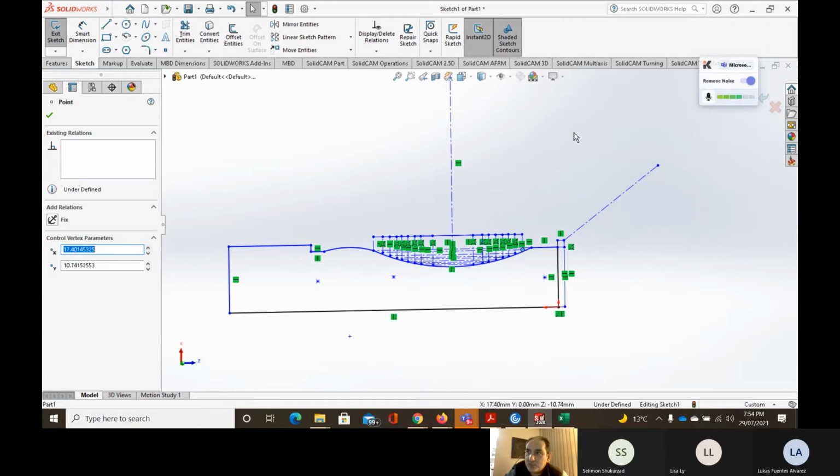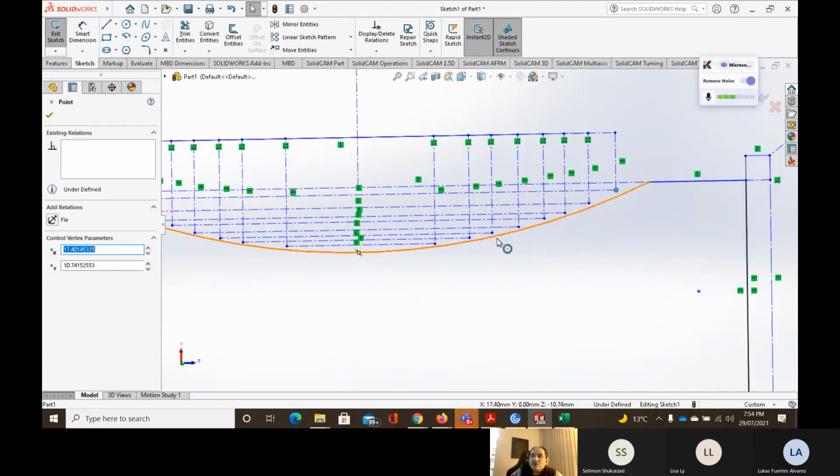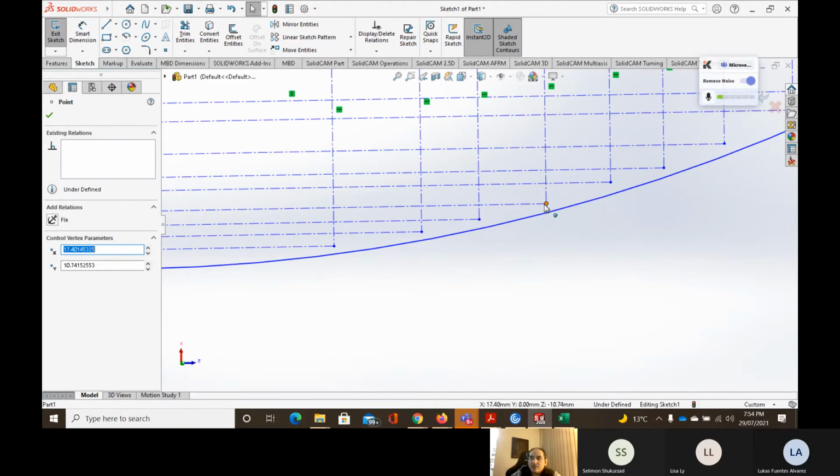The tip of the cutting tool will be exactly on the location where we want to cut. Unless we have a rounded tip cutting tool like the carbide insert, where the radius is going to be something about 1 millimeter. So you only insert that into the machine, and it's going to do the offset by itself.